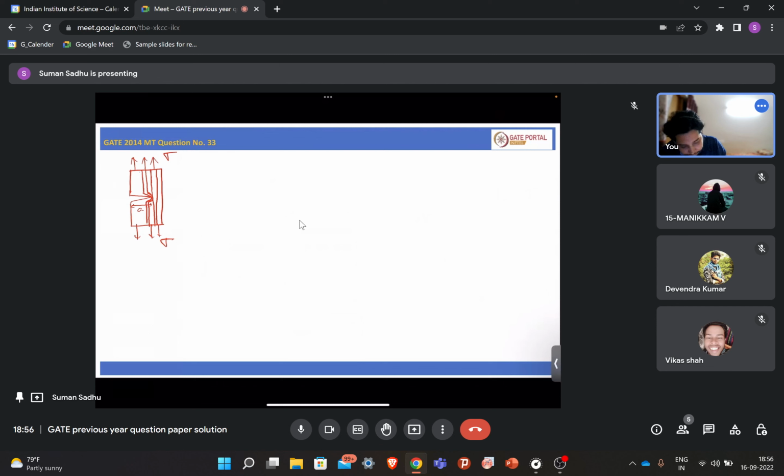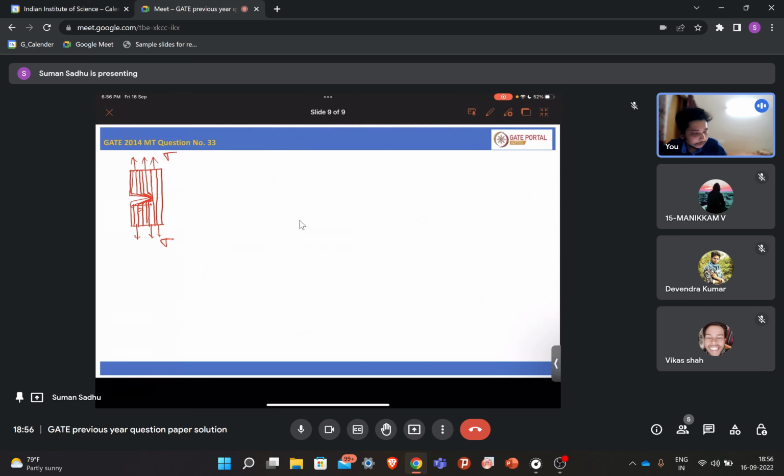So what will happen? A large amount of stress will get concentrated near your crack tip. So in this case, your deformation will be concentrated near the tip itself. Initially your tip was like this. Now when you are loading, too much stress will be concentrated here. Let's say this is the distance from the tip, x. If the stress we are applying is sigma, then at a very far distance from the crack tip, your stress will be sigma, right?